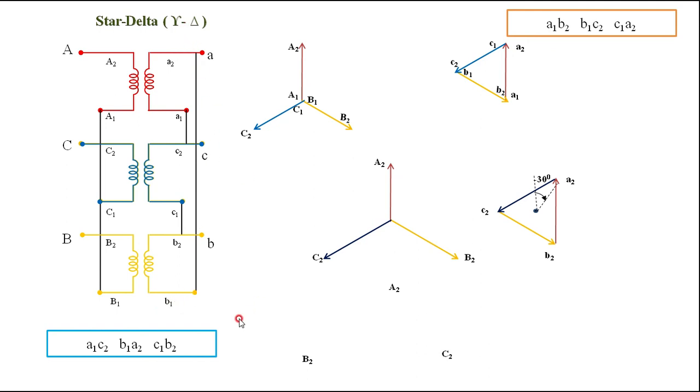This is a connection. For this, what is my phase sequence here? It is ACB, therefore here it is A, that is the voltage across this. This is C, then the third one is B, that is the primary side. The corresponding, you can shift here as A, this as B, then this as C. In this case, the neutral is shifted 30 degrees, a leading shift of the neutral, for the connection of ACB. What I mean is, when you are connecting in star to delta, there is a phase shift of 30 degrees.